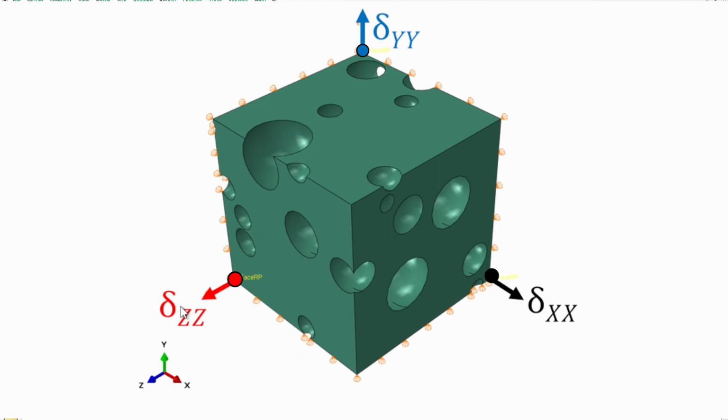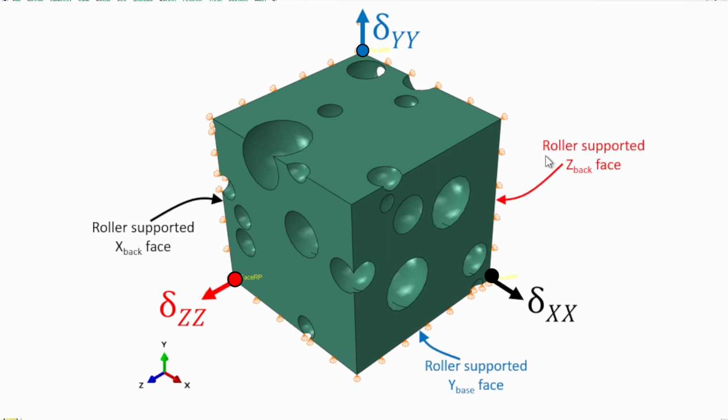to reflect this triaxiality. And the interesting thing about that is that if I'm applying load in the x direction, I need to then hold the back direction so that I have a pure uniaxial deformation. And the back end here is only going to be fixed in the one direction, so it's then free to contract in the y-axis. Now, with respect to the y-axis, if I'm going to pull in the y direction, then I need to also hold the base here, which means I'm fixing it in the y direction of the 2 axes, so that again it's able to contract in the z-axis and the x-axis in this instance.